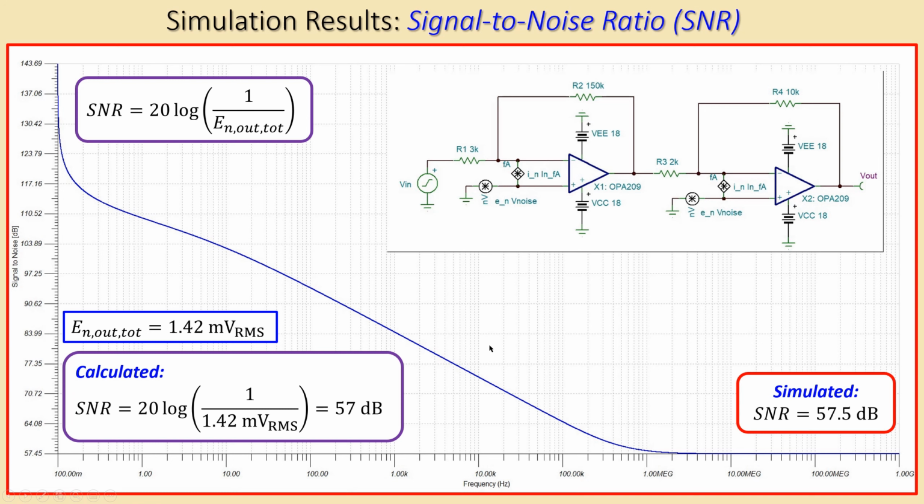Alright, this was our example using a two-stage amplifier. You can see there are several steps to be taken. You need to consider each stage separately and then add them up using, of course, again the root sum of squares because we are working with noise powers. Then we verified this in our SPICE simulations. The result in the simulation for the output referred RMS noise voltage was first 1.42 millivolts RMS, and we then made a better estimation by using the average value of the noise bandwidth conversion factors, and that resulted in a much closer value between the simulation and the calculations.